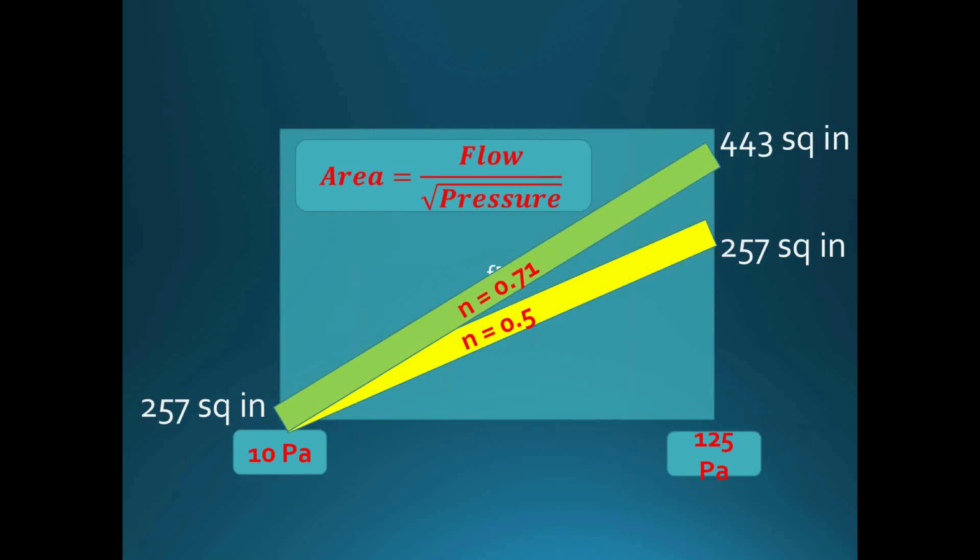So you can see by using the old test method that we don't get the advantage of the slope that might actually be occurring in the room that will allow us to pass both peak pressure and hold time evaluations. It doesn't really matter if you understand this. You put the numbers in there, you do the measurement now at 10 and 50 pascals for measuring enclosure leakage, and you automatically get that benefit.